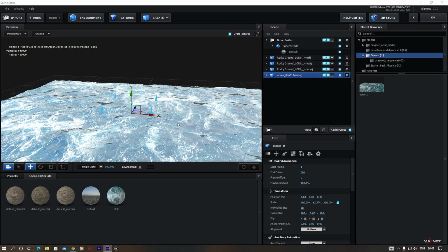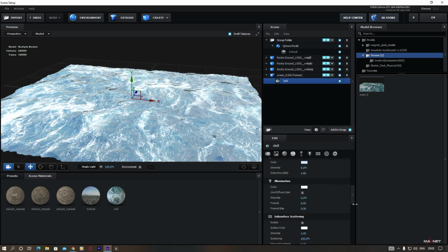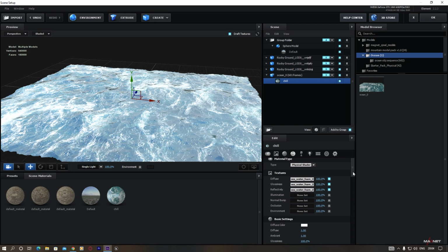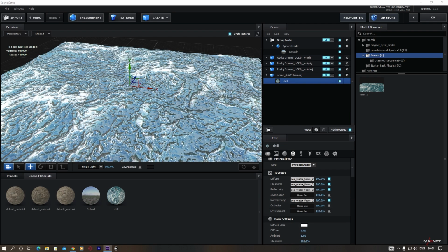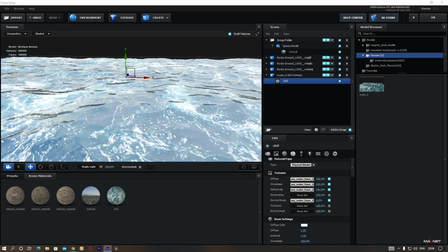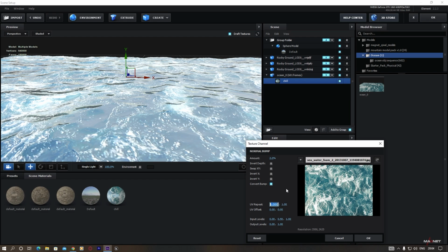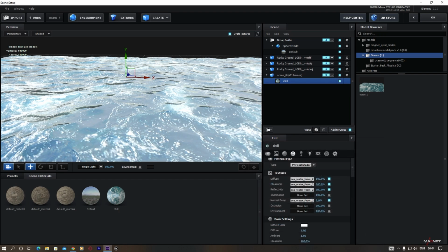Okay, so now we're going to change some texture settings for this ocean surface. So just expand this ocean model here and go to its properties for the material. So first we go to the top here and we copy this diffusion texture here. Just copy this and then paste it to its normal bump channel. Okay, but you can see that the bumpness is very high here, so you're going to change the amount down to maybe 2. Okay, so it creates a nice result. As well as we go into this here and we change this repetition value to maybe 2/2. Okay, and then hit OK.